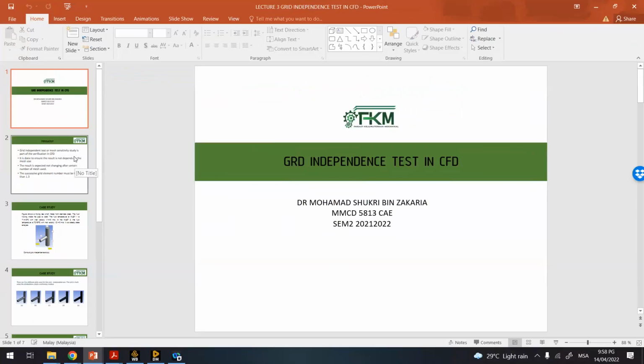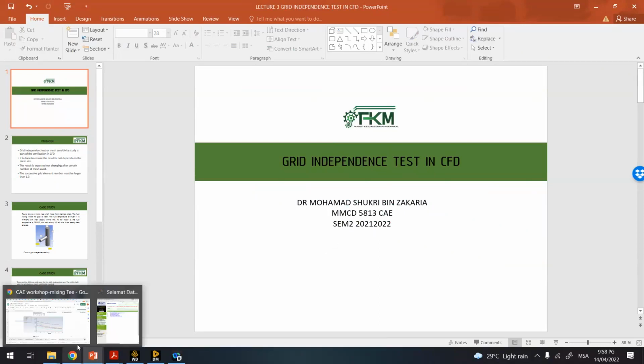This slide I have also uploaded in Yulian, so you can refer. One of the criteria for verification is the grid independence test. Grid independence test is compulsory for any simulation work, particularly in CFD or FEA. You must do the grid independence, like what we did last Tuesday.